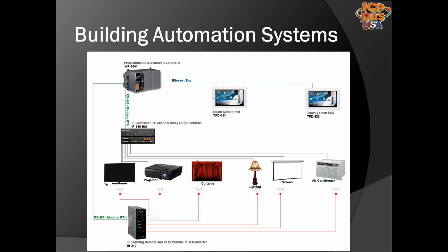Industrial building automation systems may include boiler controllers, package control units, VAV (variable air volume) boxes, PLCs, lighting controllers, BACnet, and LonTalk devices. A primary bus is often used for higher level controllers or programmable logic controllers, and secondary buses may be used for input and output devices and user interfaces. Open standard Zigbee wireless mesh networks are often used in building automation systems. Building automation SCADA systems can show the status of large or small systems on computer screens.